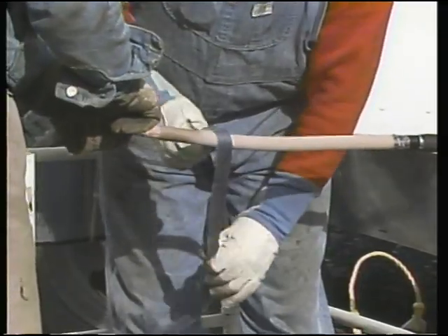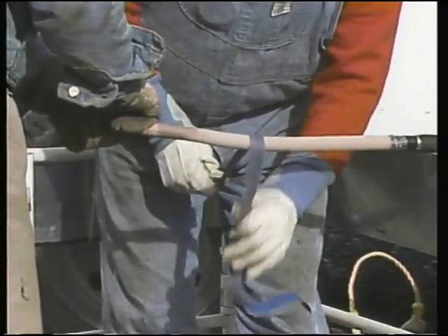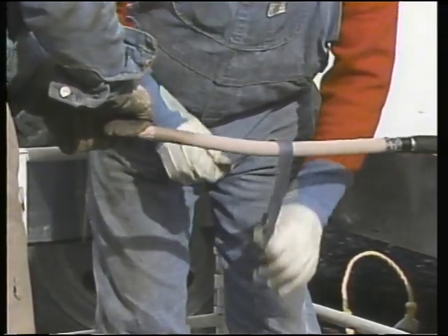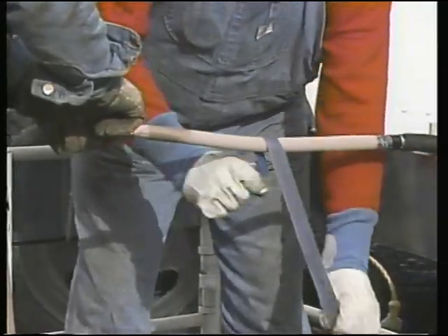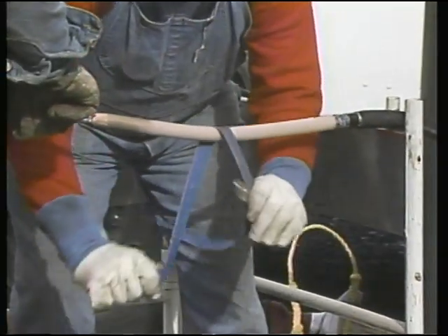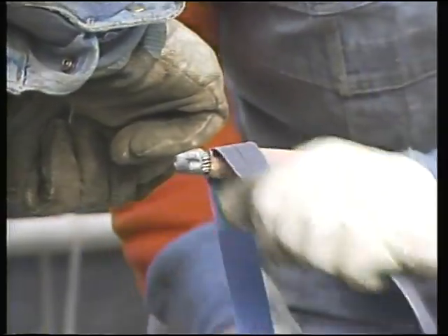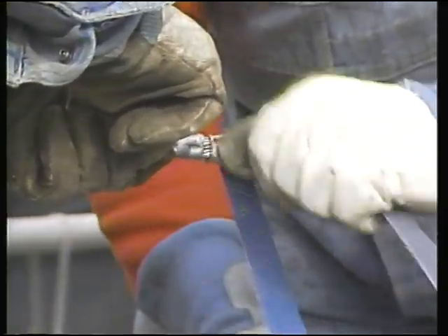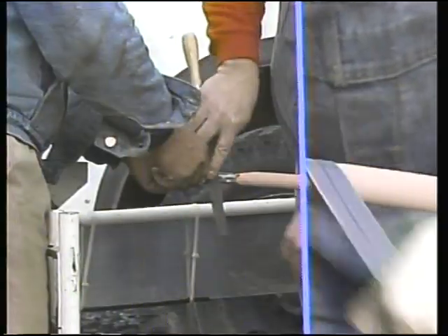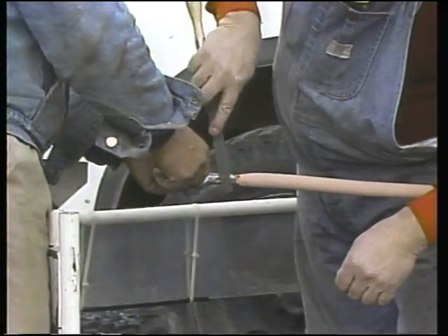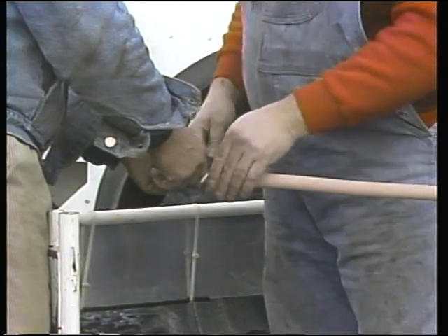Next, the insulation is sanded with a non-conductive sandpaper to remove any trace of conductive material. This minimizes the possibility of tracking between the cable conductor and the insulation shield. The penciled insulation is sanded to smooth out the taper. Then the compression lug is filed to remove any sharp edges created by the compressions.